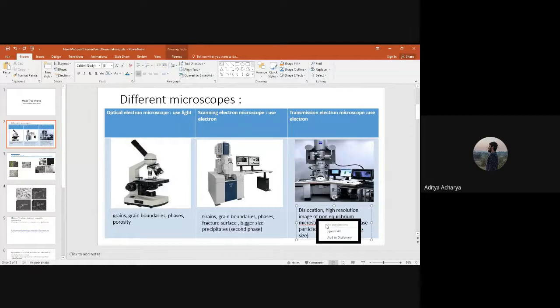Here I have a question. Do you remember what kind of non-equilibrium microstructures we have in steels? Can you name a few of them? Bainite, martensite. Very good. Who answered? Pranav. Pranav, remember the things. This non-equilibrium microstructure forms by non-equilibrium cooling. That is a very fast rate of cooling, right?